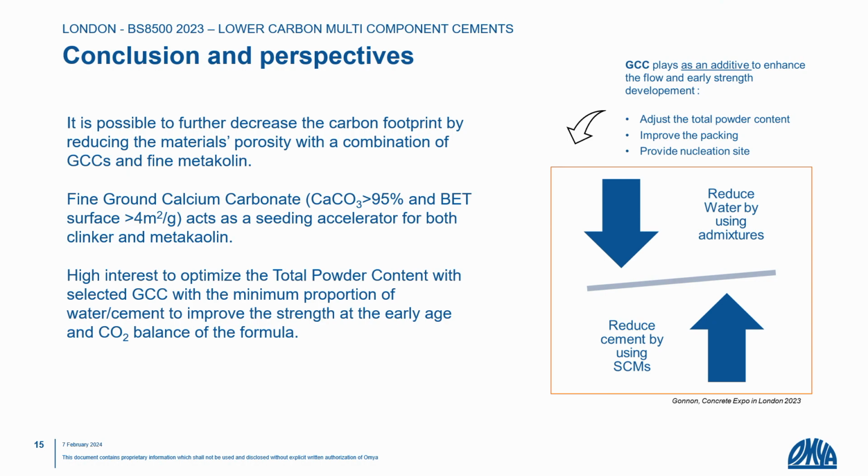The second point concerning the superplasticizer is we have seen that we need to speak about the concentration of the superplasticizer and also the viscosity. I have in the lab that I manage sometimes the target of flow, but I have an issue on the viscosity. And the other point on that is really to speak about the added value of such calcium carbonate.